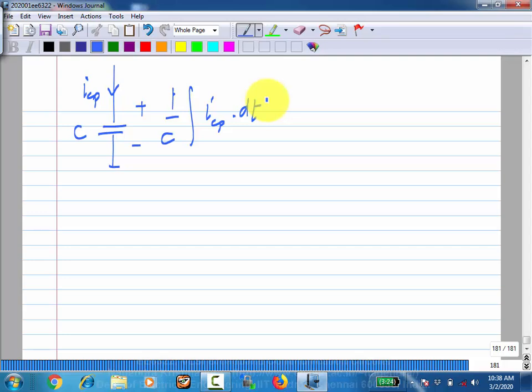So now I also said this integration has to be very slow. This is the offset that you want to apply to the VCO. I said that this offset should change very slowly so that before you see any appreciable change, the other loop should reach steady state. So what does that mean? Should use a large capacitor. Okay, we'll later see how large is large, but you expect that this has to be a large capacitor.